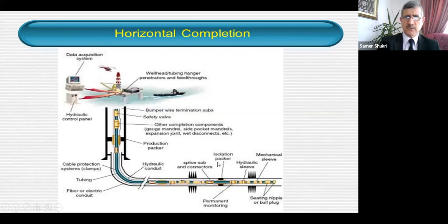So we have to ensure this specification. So we don't run first, second, third: first run down to open, and the second one run up to open. This is wrong. So all of them should have the same direction of opening, same direction of closing.